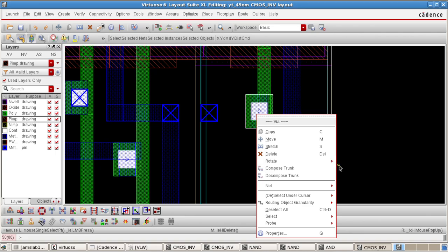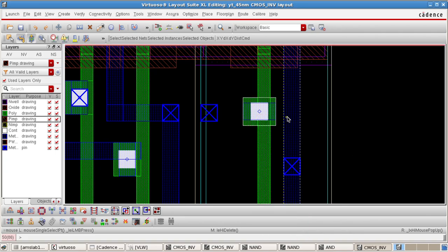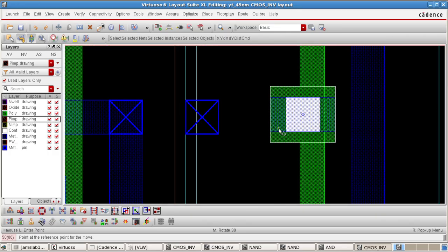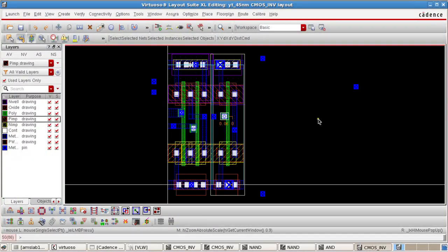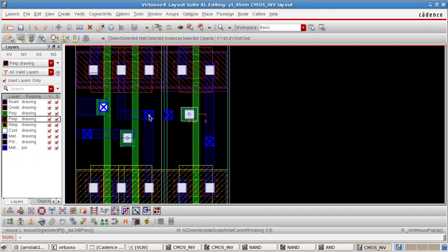now, since we have a DRC constraint, we made some extra width of metal to get the minimum area of 0.2. But now we need not have that constraint since we are connecting both at the top level. So what you can do is